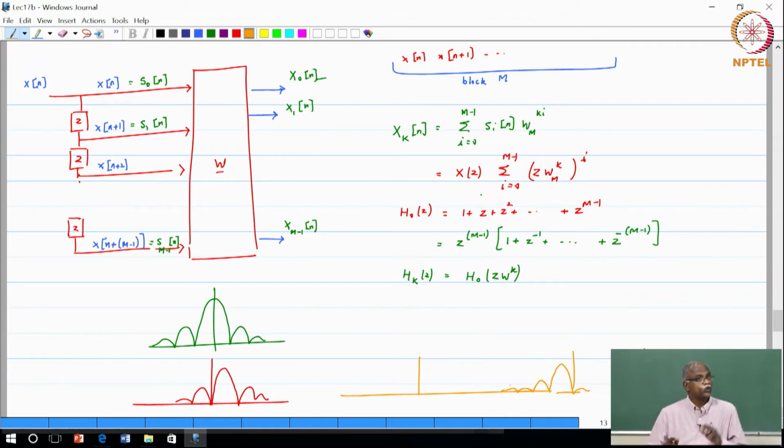Okay. So, what is DFT? It is actually taking the input signal, passing it through a bank of filters and then giving you the outputs and saying, oh, by the way, x naught, you think of it as the frequency component. Usually if somebody gives you the DFT coefficient x naught, what is your interpretation? That is the DC term. It is actually not the DC term, it is actually all the energy in your input signal that will pass through this filter is what comes out as x naught.